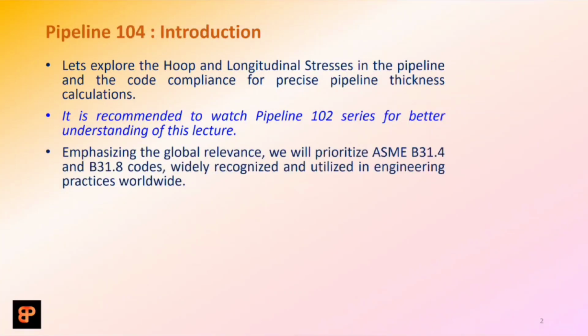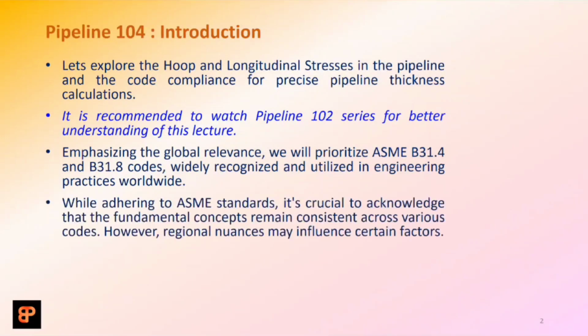We are going to consider the ASME B31.4 and B31.8 codes, emphasizing their global relevance. They are widely recognized and used in the majority of the consulting firms across the globe, and therefore it's always better to follow them and see them first. Some other countries might have their own regional nuances influencing certain factors, most probably the design factor or certain criteria. However, the fundamental concepts shall remain the same.